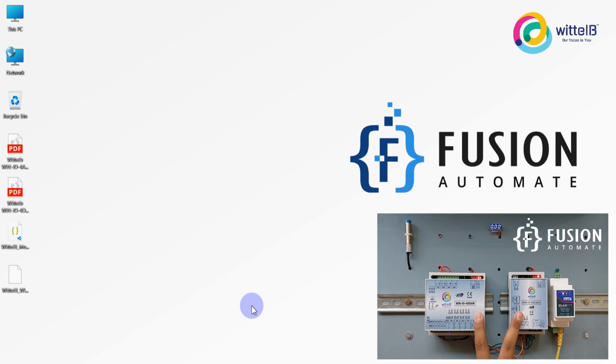So this Modbus IO card is serially connected with this ZLAN5143D gateway, and this gateway is converting Modbus serial data into Modbus TCP data. I have connected this gateway via LAN cable to my laptop.